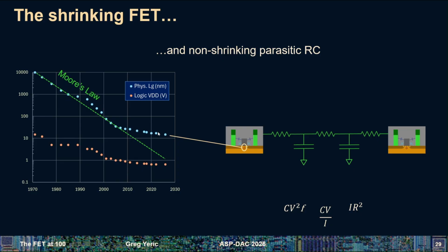It's famously, we're not scaling the gate length like we like to, according to Moore's law and Dennard scaling. But that's actually not that big of a problem, given all the parasitic capacitances are dominating. Outside of looking at an individual transistor, there is also this parasitic connection capacitance. That's going to get lumped into the C of a circuit, where CV over I has the units of time, so that's your delay metric.